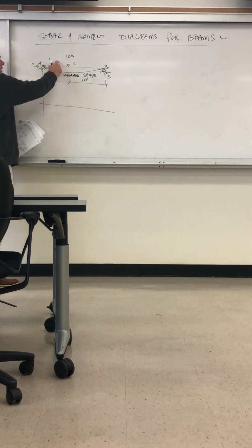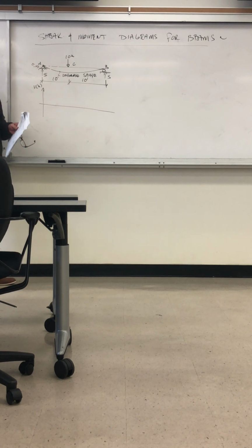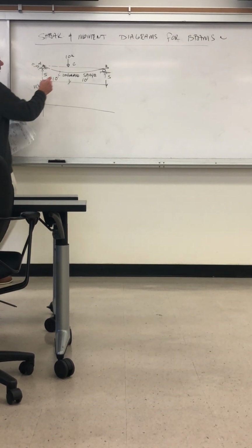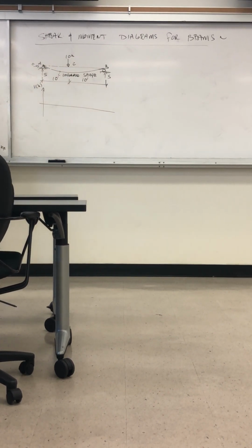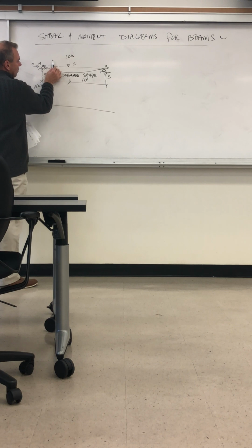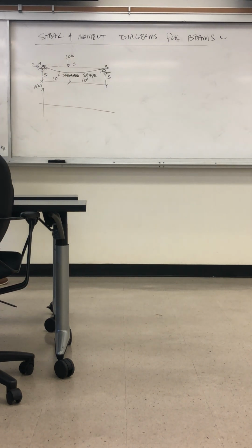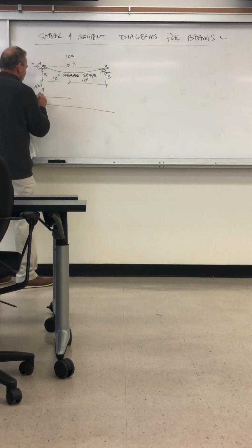And if I take a cut here, that's still 5 kips, right? There's a force up that the whole cross section is resisting through shear stresses. Shear stresses of VQ over Ib. There's also a bending moment, but let's talk about that in a minute. Until we get to this point, if there are no loads applied down or up along that length, up until we get to some load, like 10 kips, every section is resisting 5 kips. And if it overloads the structure, then it won't be resisting it and it will fail, right? You'll yield, damage and fail the structure. So we come to this point, it's constant, so you stay fine like that.